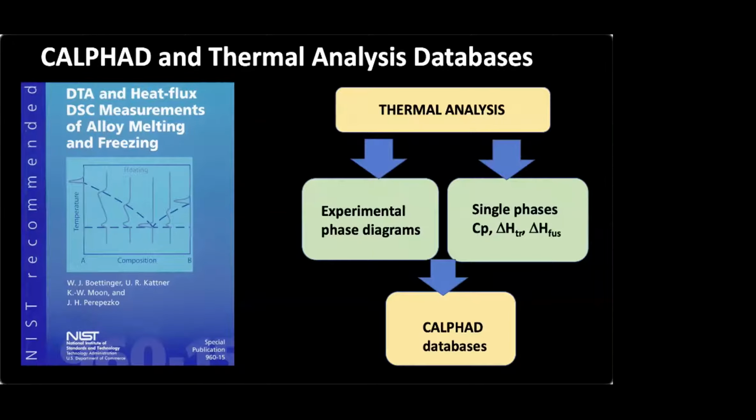At the end of my talk, I would like to bring up the subject of CALPHAD and thermal analysis databases. Of course, thermal analysis contributed greatly to development of CALPHAD databases, first by providing data for single phases, such as heat capacity and enthalpies of transition and fusion, and then by determination of experimental phase diagrams. I think every CALPHAD user is well aware of thermal analysis. However, I don't think the reverse is true.